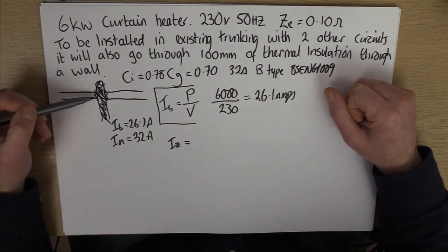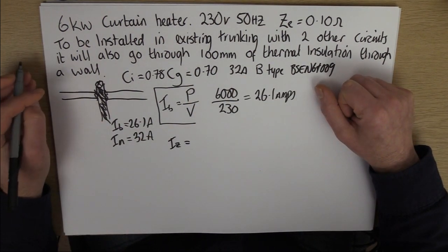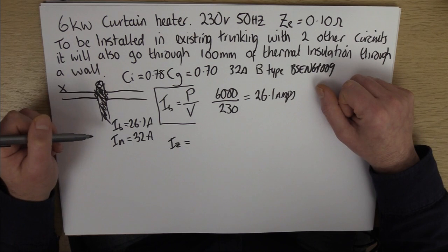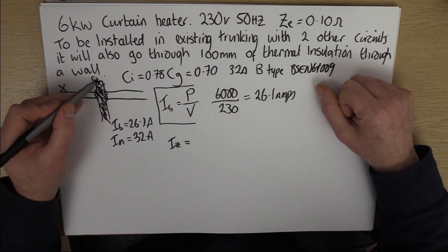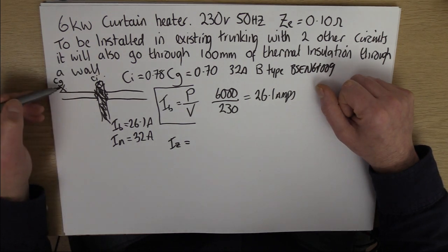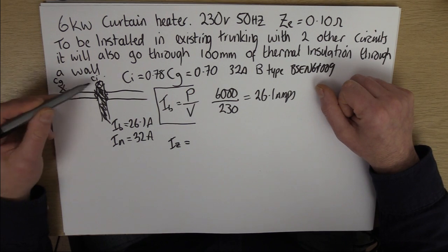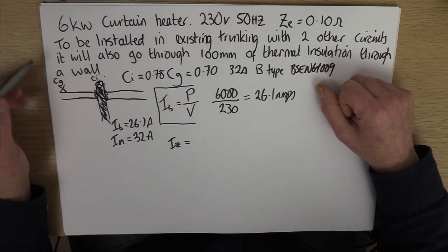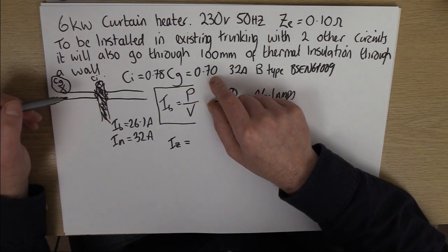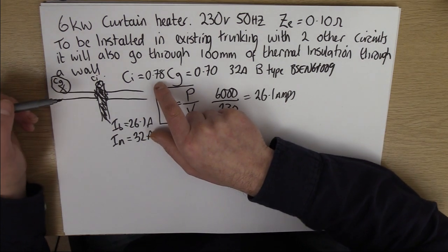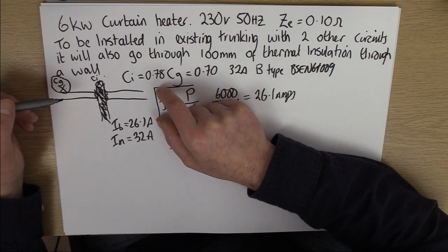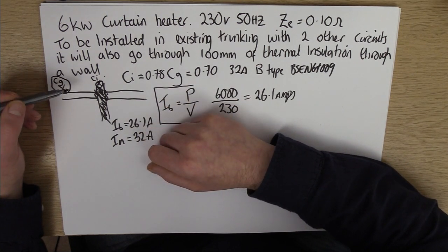With these grouping factors, incidentally, if, say, there was no grouping here, yeah, we got the CI occurring there, and then it only grouped there. Yeah, that makes more sense, great. Then essentially we would take whatever the worst one is. So in this case, that would be the grouping factor. 0.7 is going to increase our CSA more than 0.78. Essentially, under 1, the closer you get to 0.5, the closer you are to doubling the CSA.